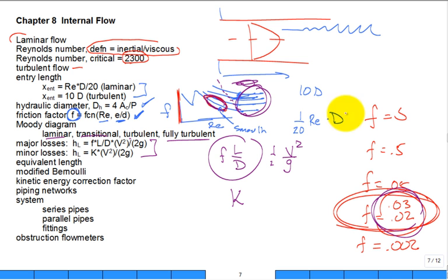Those three forms, 1/2 rho V squared, 1/2 V squared, and 1/2 V squared over g. And I think if you get that down, it'll save you a lot of units problems as you go and solve problems. But you multiply that times whatever. This is your dynamic pressure or velocity pressure, or it's your dynamic head, whatever term you want to give it. That 1/2 V squared over g, I would call that my dynamic head.